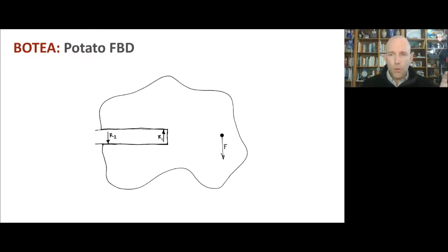So if we assume no friction and solve for what these reaction forces need to be, we will get bigger reaction forces, normal forces here, than we would get if we included friction, because these forces arise as a result of the need to counteract the moment caused by this rope force. Well, the friction forces would also help counteract that moment. And so if we remove those friction forces, then these forces have to get bigger. So all those things say, it's not too big of an approximation to neglect friction, and it's a slightly conservative approximation. So we could probably work from there.